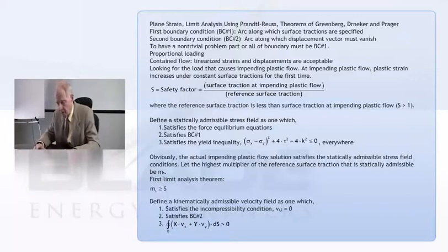And the way we find the lower bound is we have to find what they call a statically admissible stress field. In a way, it's kind of a guess, because this isn't a full solution, but it's part of a solution. And once more, if you think of elasticity, you do minimum potential energy type theorems.